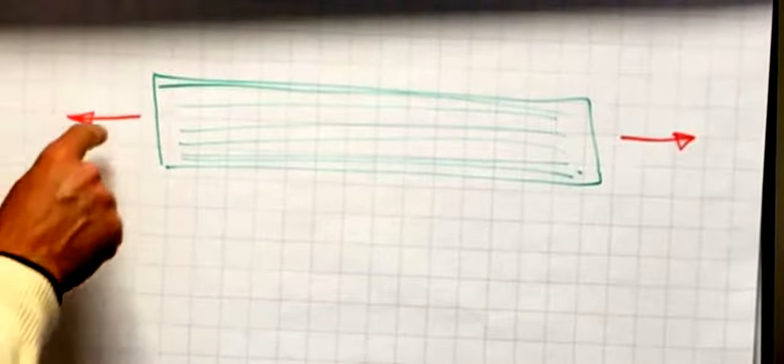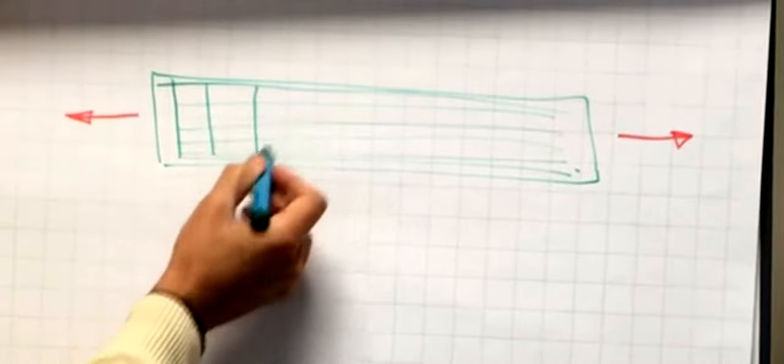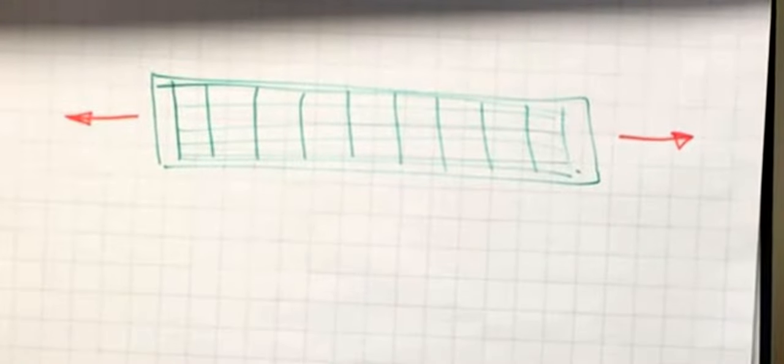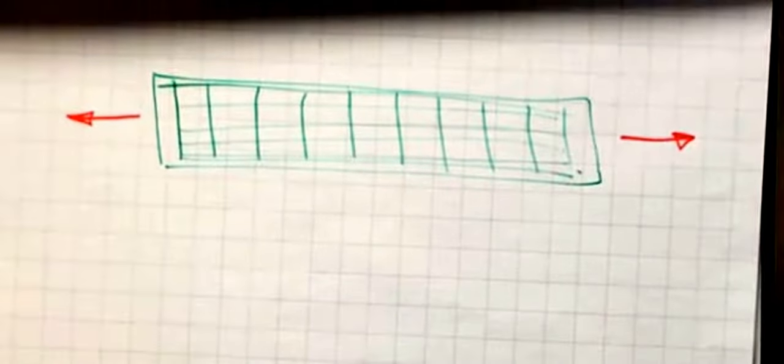But in real life we don't have material like this. A pipe is always a shape that has a bidirectional loading. So there is not just a load, say, in the longitudinal direction, but if you have a pipe, there is also a load in the circumferential direction. So there's a bidirectional load. This means that we also need fibers in the other direction. So we have fibers in the other direction as well. And basically we have alternating layers of fibers in the one direction and fibers in the other direction, as layer to layer they differ.